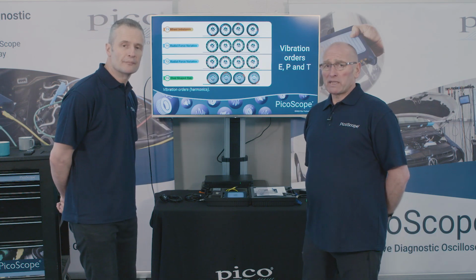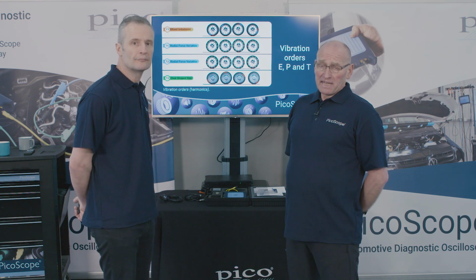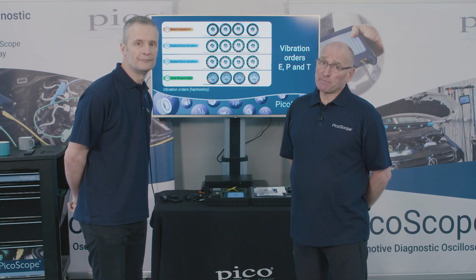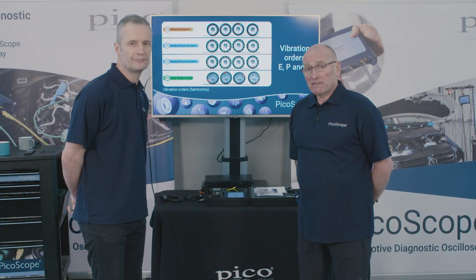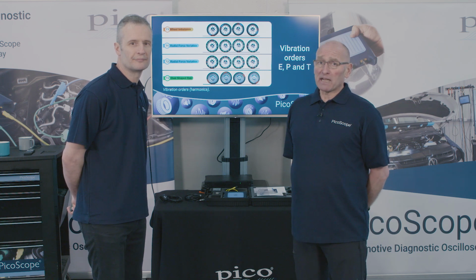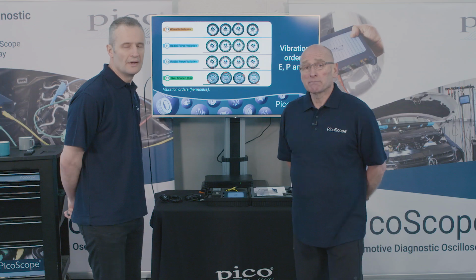Also be aware of the fact that when a vehicle is new, the manufacturer will identify a high spot on the rim, and the tyre manufacturer identifies a high spot on the tyre. When correctly fitted, these are normally set 180 degrees apart to minimise out of balance forces. And regrettably, when the vehicle ages, we no longer have that ability. So quite often, a second-hand vehicle with older rims and older tyres does suffer from this vibration issue because of incorrectly paired components, basically.